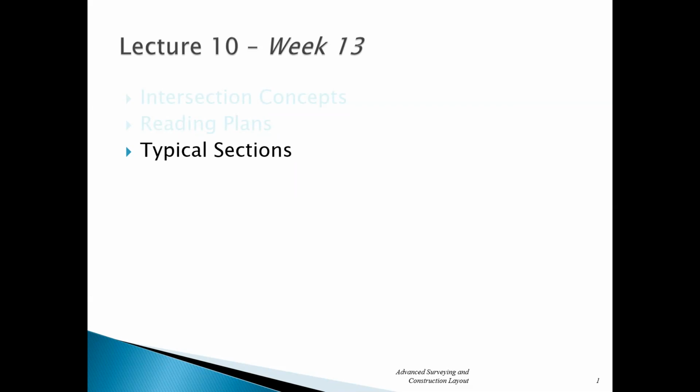And in our case, we found there was a relationship between the center line and the back of curb. It was what, 0.2, wasn't it? I think. Yes. 0.2 feet. So that was the same throughout the whole process. But if we have other things going on left or right, like ditch sections and those kind of things, that can change a little bit too.